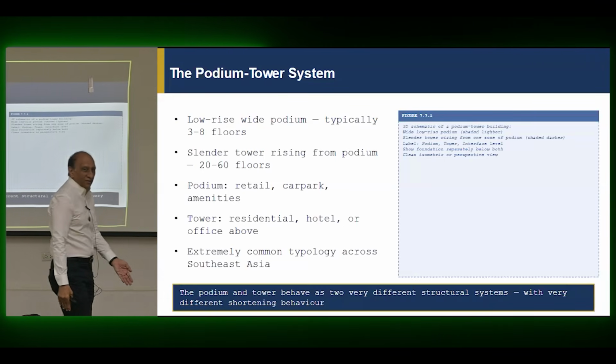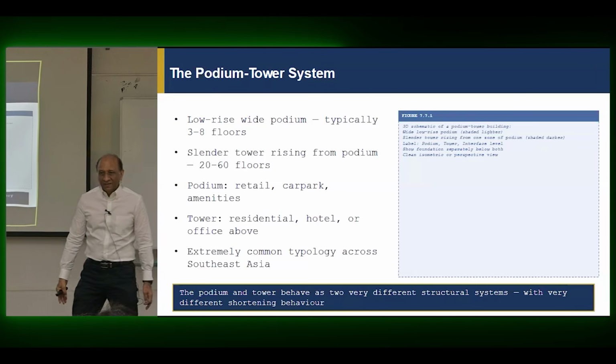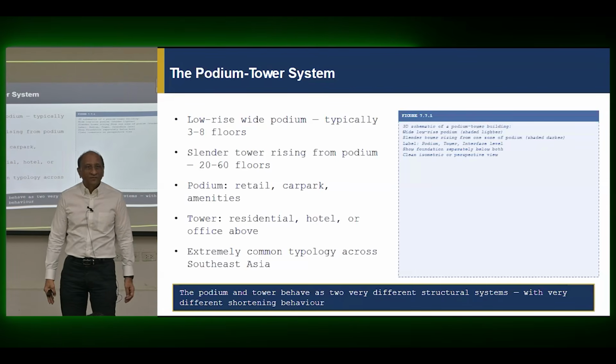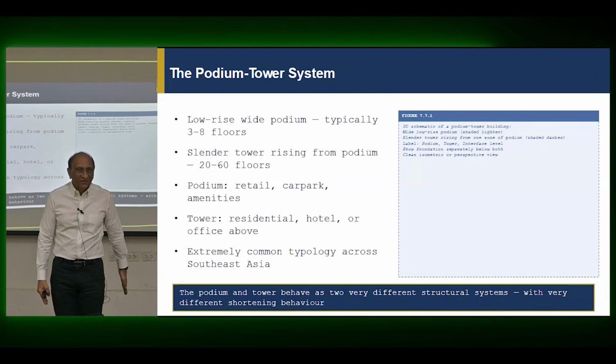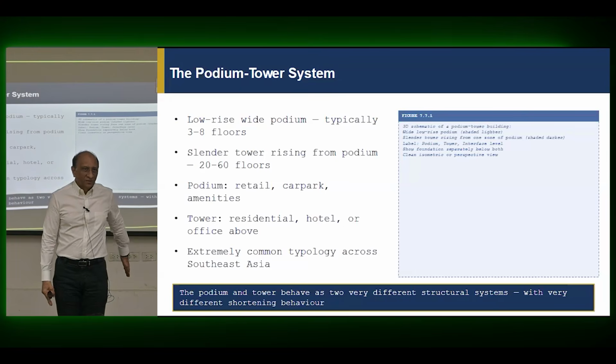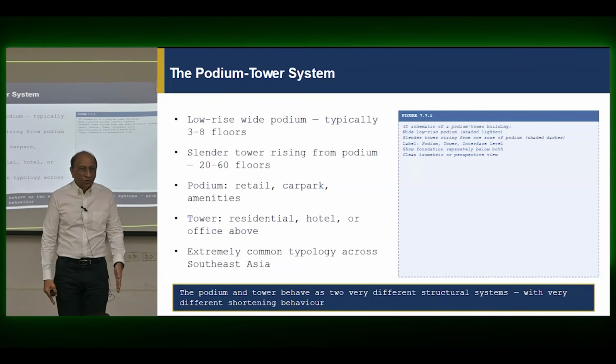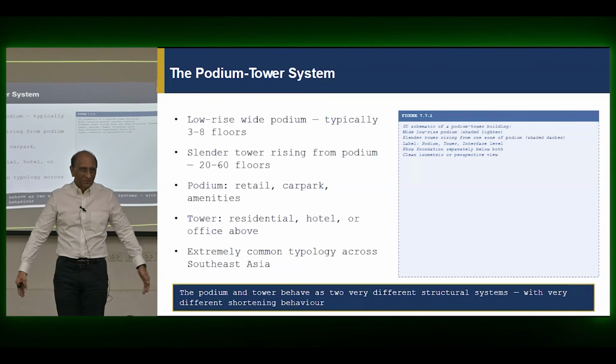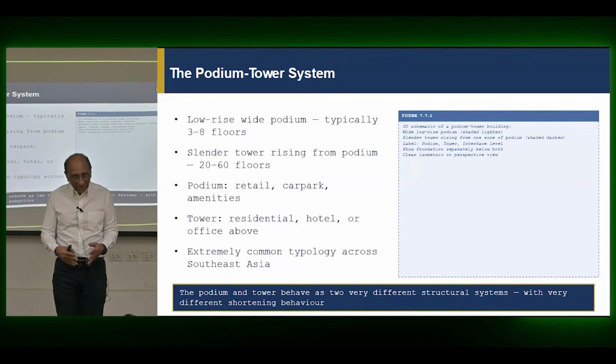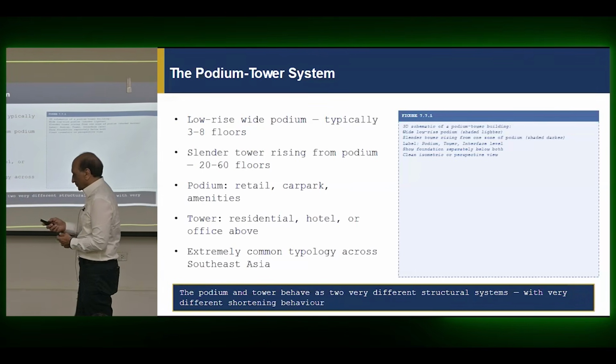This side is just 4 floors. That side is under the tower. We can't see the difference. But imagine what is happening at this interface. From the long-term effects, from the axial shortening, from the soil structure interaction, from soil pressure, so much is happening in the two regions. So we need to manage this problem well.